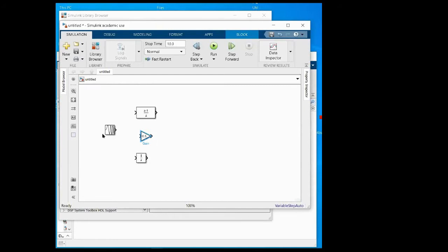Let's connect. To connect different blocks, we have two ways of connection. I can take my mouse button and just connect this output from the first block to the input of the other. Another way is to select the block, press the Control button on the keyboard, and then press another one which should be connected. Let me show how it works. I select the first one, press Control, and press the second one. This is a way to connect several blocks quickly.